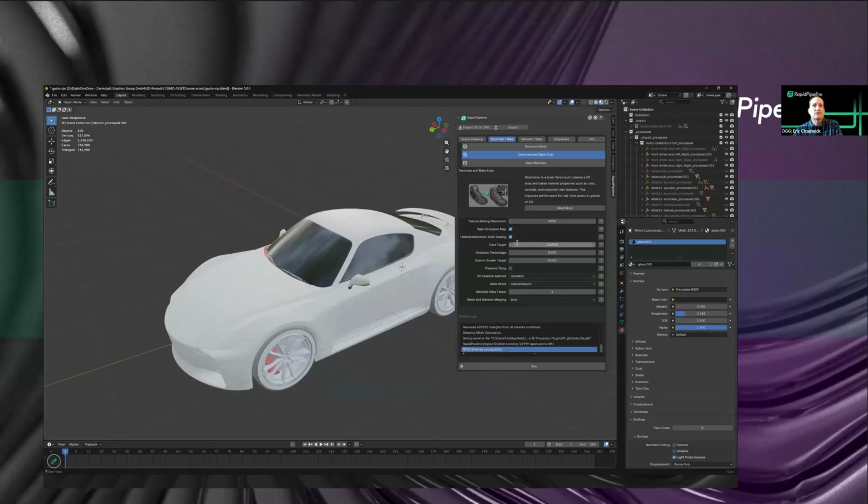And then the decimation target, let's go down to 50K for this car. So it's 50,000 triangles instead of 784K. Deviation just gives you curve-based decimation. So it looks at the overall curvature of different surfaces. And if it can go lower than 50K, it will, based on this kind of a quality metric. It's a quality-based tessellation or decimation target.